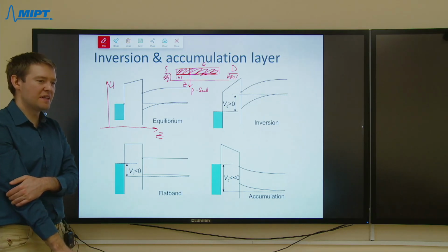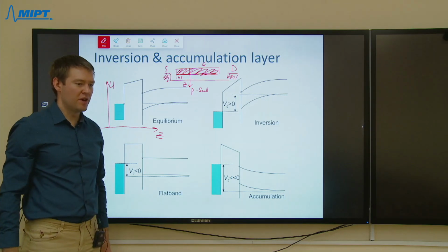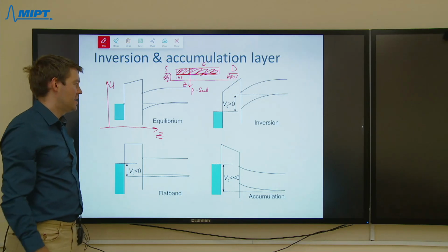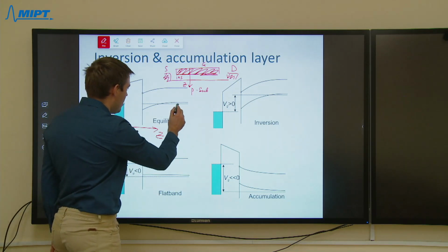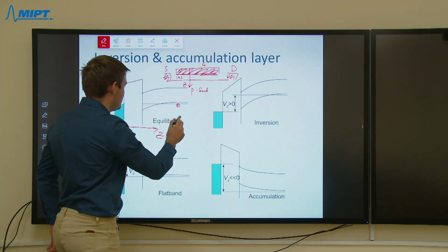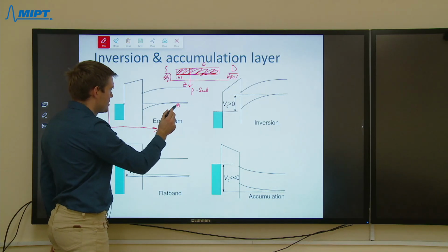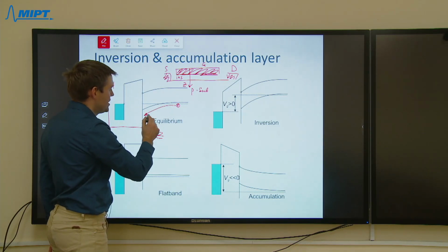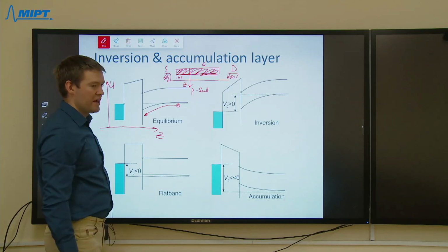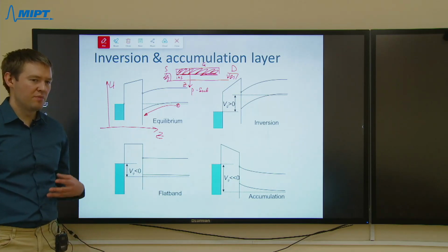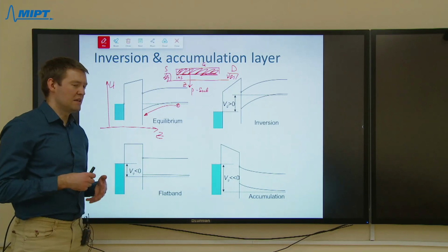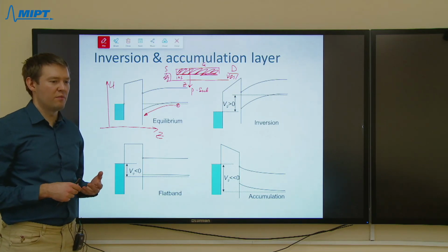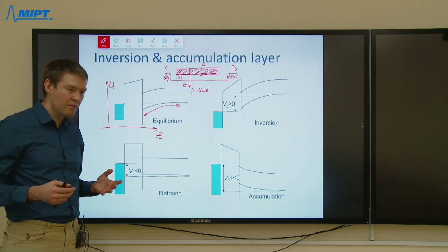So this is the same as we had in the theory of Schottky junction between metal and p-doped semiconductor. A hole that would like to traverse from semiconductor into metal sees a potential barrier on its way. And this potential barrier actually prevents diffusion and is responsible for the formation of thermodynamic equilibrium.